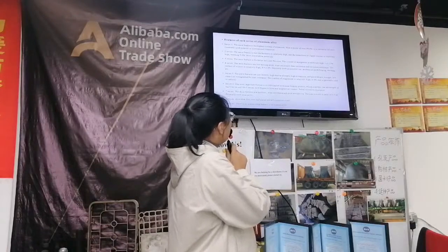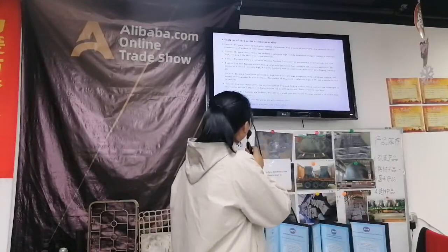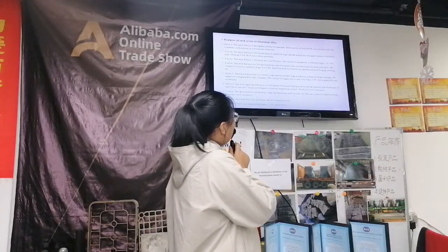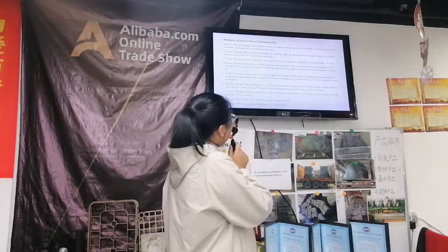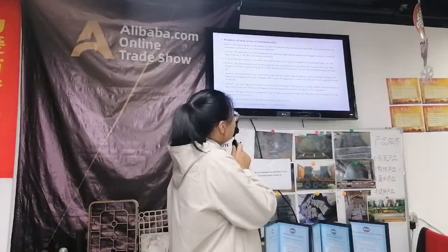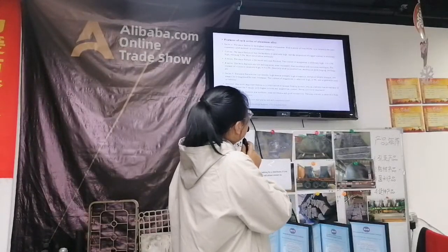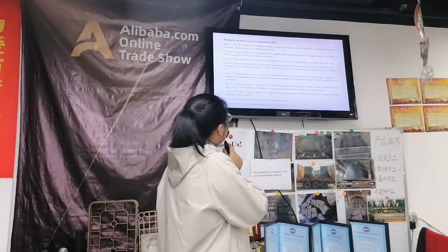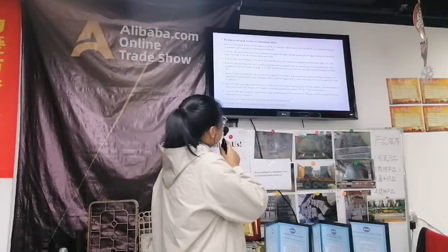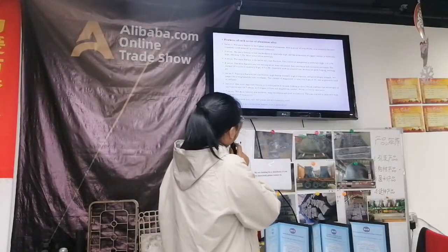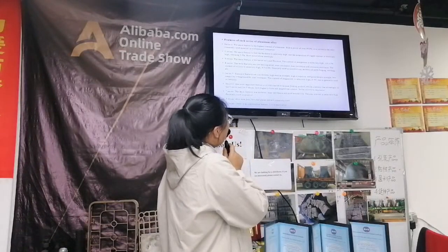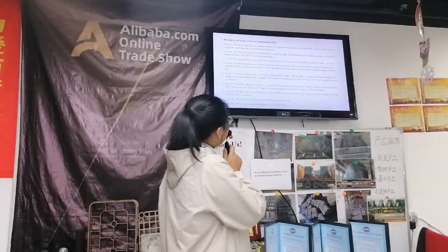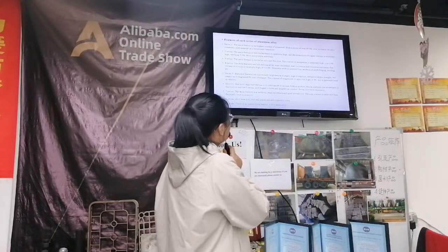Features of each series of aluminum alloy. 1 series: the main feature is the highest content of aluminum, with a purity of over 99.0%. It is the most commonly used material in conventional industries. 2 series: the main feature is that the hardness is relatively high, and the percentage of copper content is relatively high, reaching 3 to 5%. Most are aviation materials.